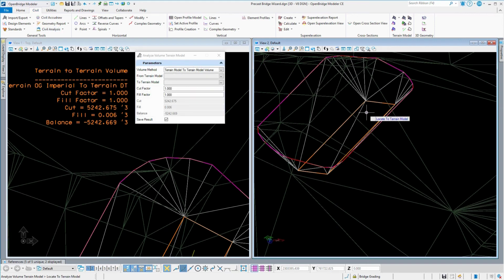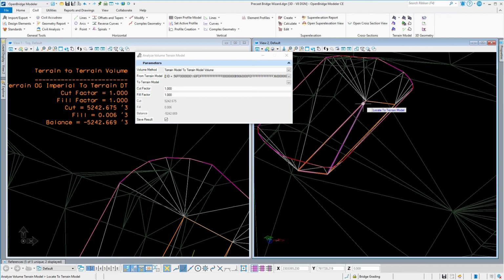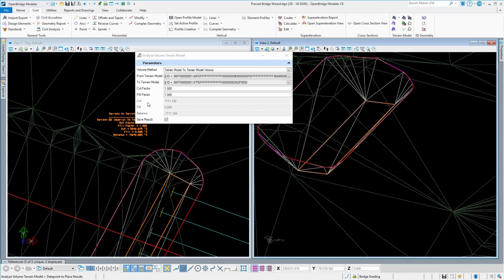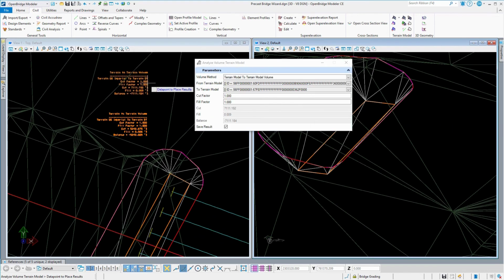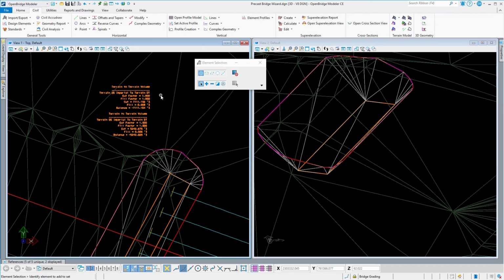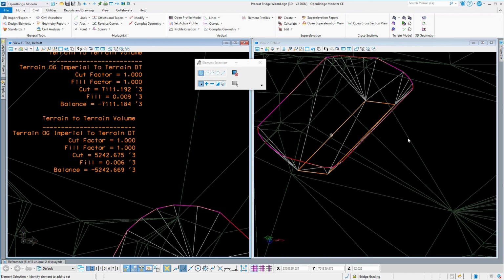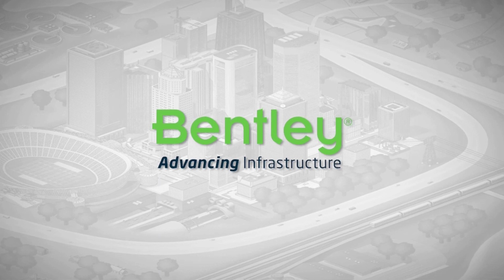The purple line that you see here, the projected slope, remains on that intelligence as it was created. So I can just do the same. It recreates the new terrain and then I do a new analysis of the difference between existing and the terrain excavation.